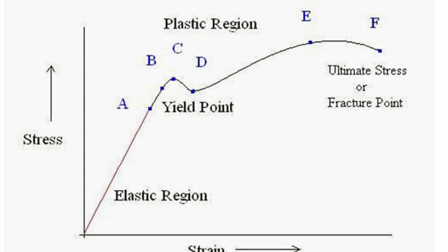So in the graph we can see that E, the ultimate tensile strength, is more than the yield strength. So we are designing on the basis of the yield point, because after the ultimate point the fracture will happen and the material will not return to its own position. So from this test and curve we can understand what yield stress and ultimate strength are.